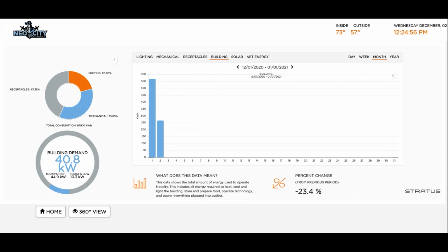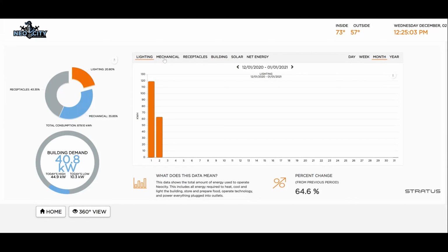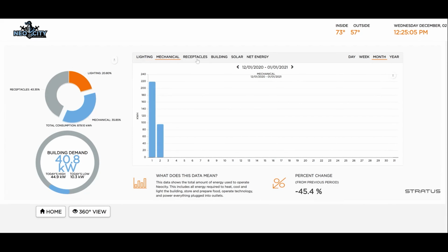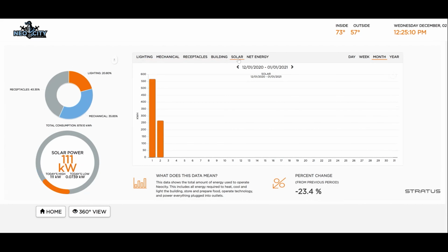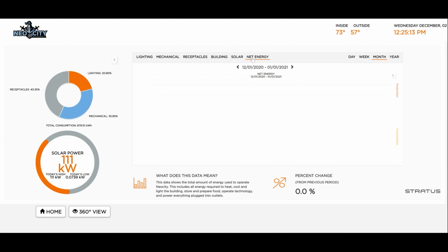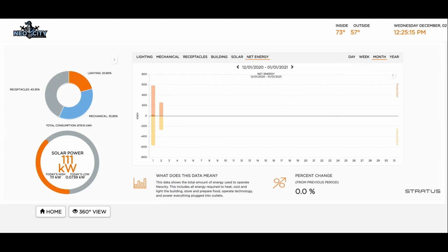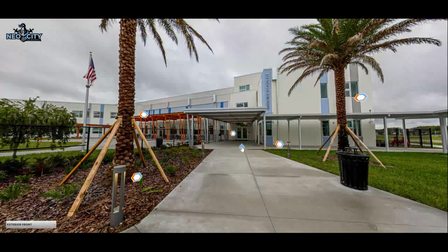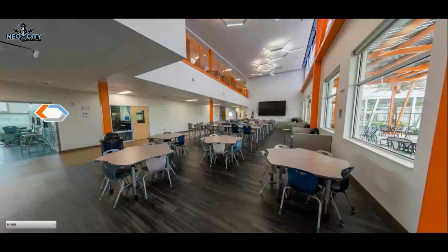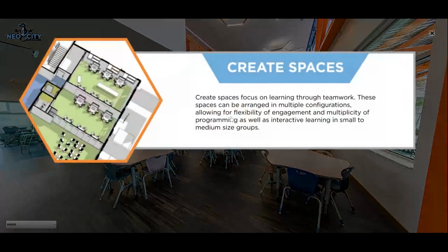But if you know where you want to be and you start to monitor it and you see it's not performing there, you go and search and you find out why. And so people like me who do this all the time, you get a little obsessed because the dashboard is live, the data is there. And if for some reason all of a sudden the HVAC system is now consuming 20% more than you intended for it to do, it gives you a trigger to go find out why. What happened? Something created this change. And we found out recently that they shut off their energy recovery wheel. That we did not anticipate, but somebody overrode it off. Now we got to get it back on.